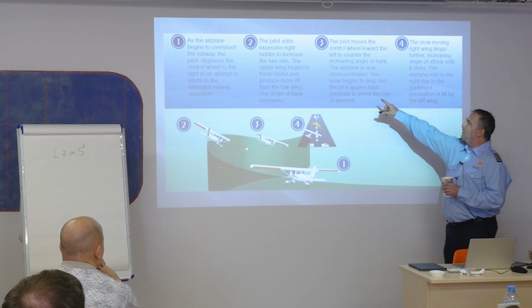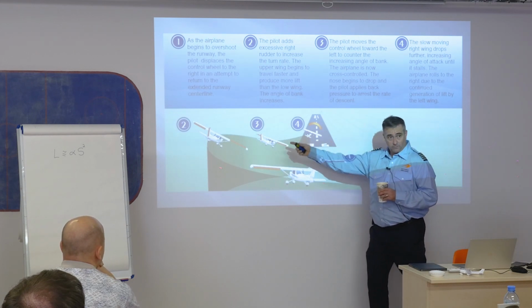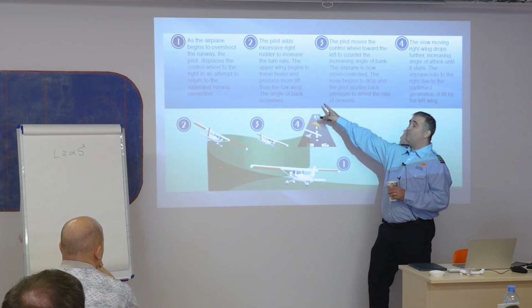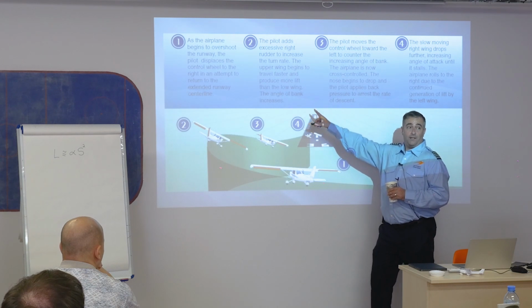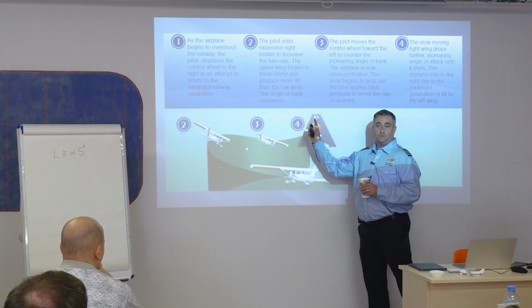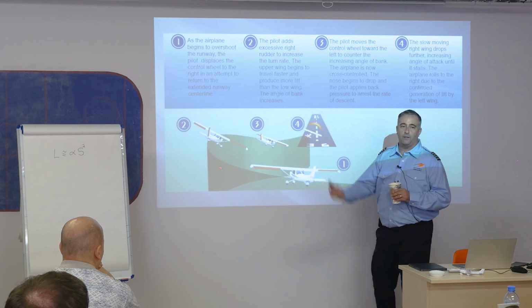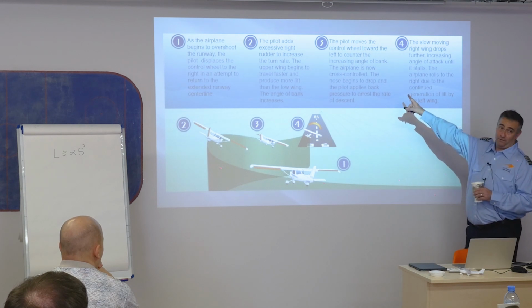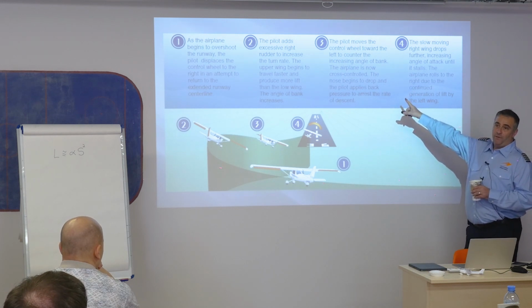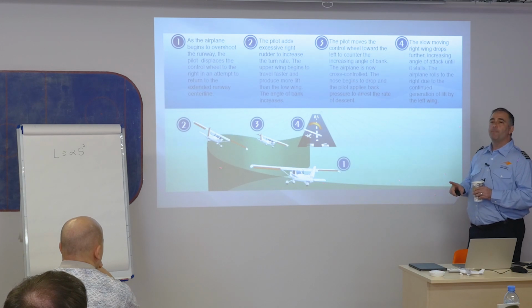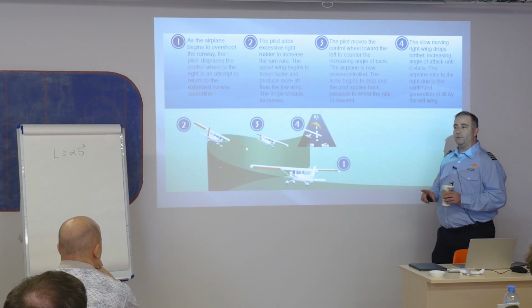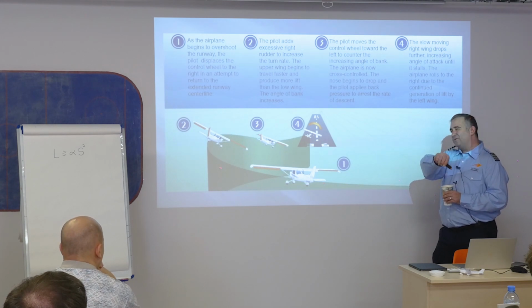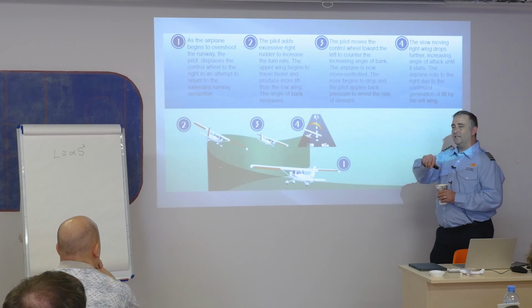Might not be though. The upper wing begins to travel faster because that circle idea still exists. That upper wing is going to travel faster, produces more lift on that wing and causes an increased bank angle. Well, if you get an increased bank angle, what do you do with the ailerons then? All right, moves the control wheel towards the left. This pilot is close to the ground and they have a right rudder pressure and a left aileron input. Does that sound correct? It doesn't.